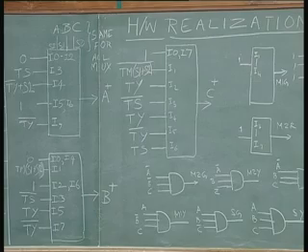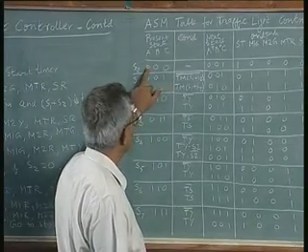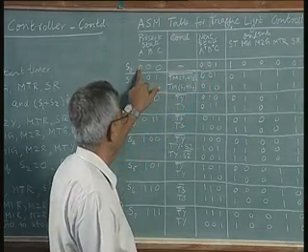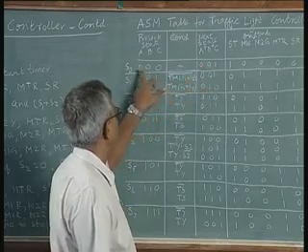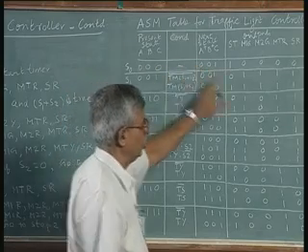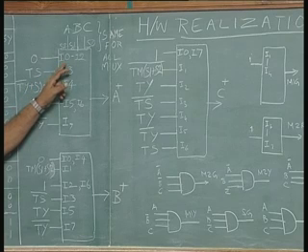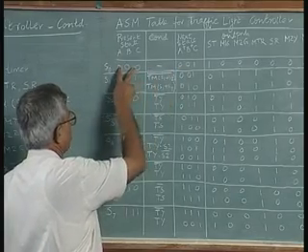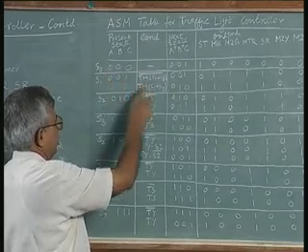For example, when you are in state S0, the condition under which the next state is 0, for the first input of the first multiplexer corresponding to A, you give 0 as the input, so I0. Wherever there is 0, we have combined them: I0, I1, I2 are all zeros, because the first 3 entries are all zeros. I1 corresponds to the first state, I2 to the second state, I3 to the third state.